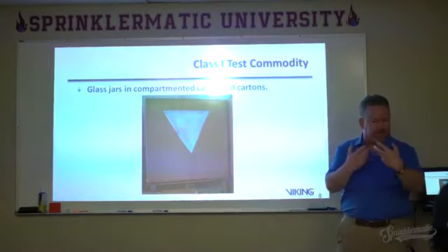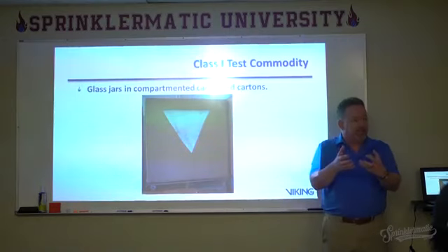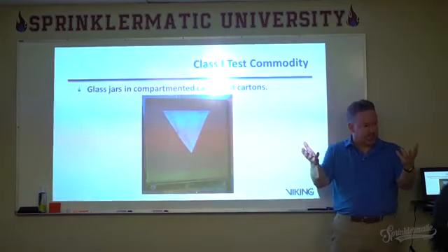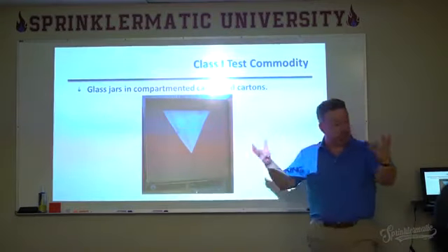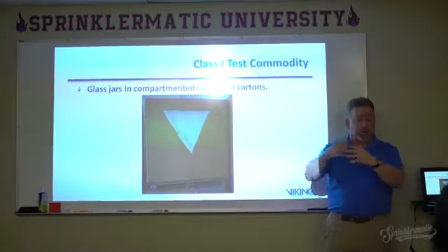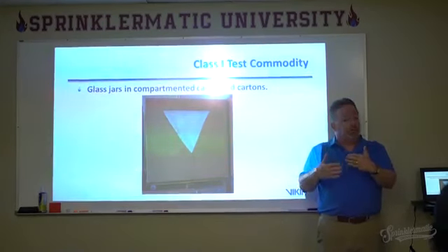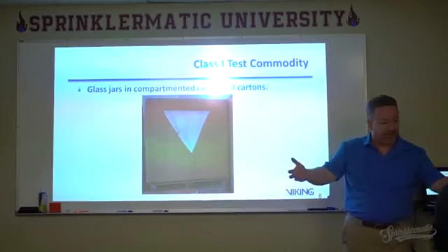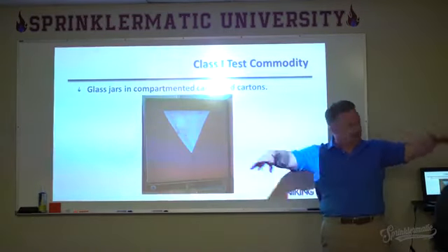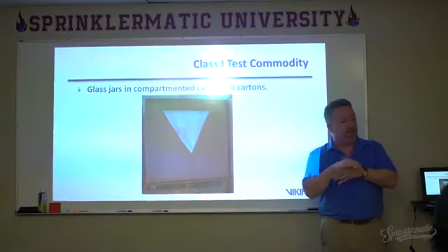So we kind of live and die on required delivered density, because then we're going to build out our sprinkler systems, and we're going to select sprinklers, and we're going to select piping, and we're going to select water, whether or not we need a pump or anything else on this system to deliver an actual delivered density, which is the water that comes out of the sprinkler minus the water that gets carried away by the heat, and it actually gets to the base of the fire.